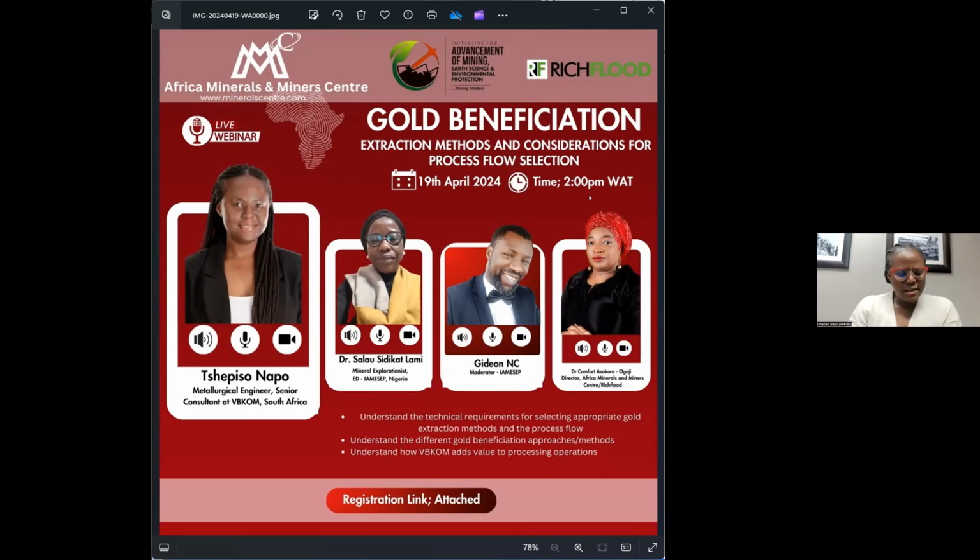Yes, ideally you would like your recovery to be above 90%. So if your study into your ore mineralogy is not as comprehensive, you wouldn't have identified your preg robbers and refractory minerals within your ore mineralogy. And these are the ones that can have an impact on your recovery.